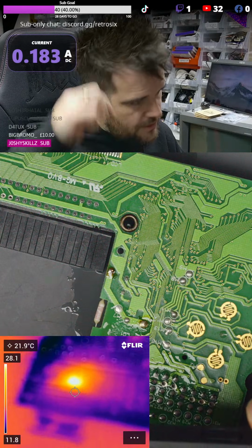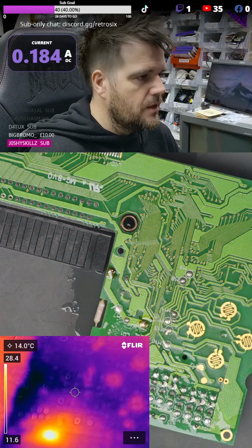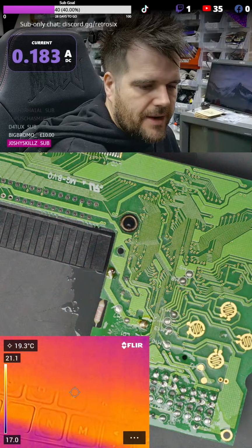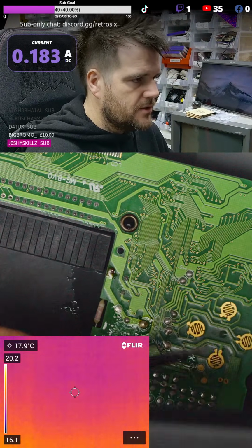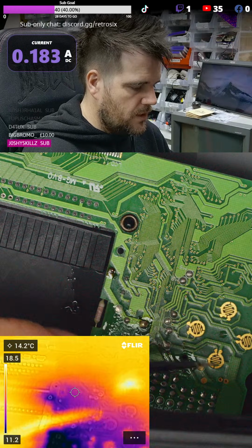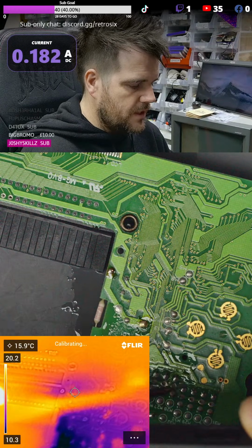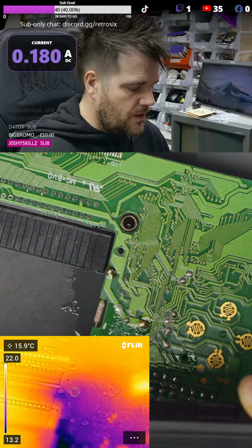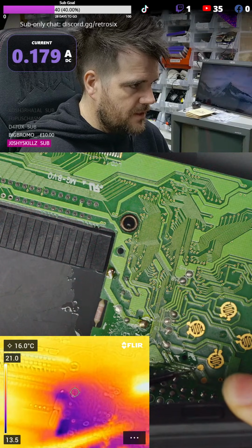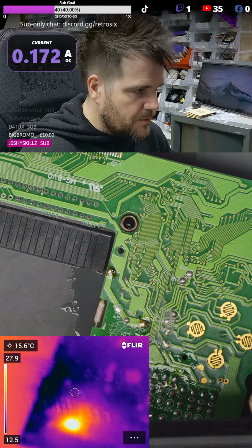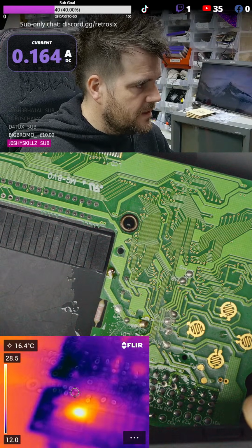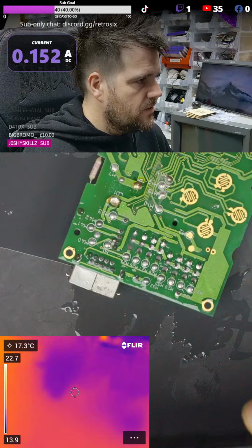What you'd now try to do is go, right, where's the short? And the best way I do is to get a pair of tweezers, soak them in IPA so that they appear cold on the thermal camera, or at least visible. So you can see on this, if I'm wafting the tweezers in front, you can just about see they're there. So you can see that tip. And then what I do is aim at the hotspot, move my tweezers in, and let's try and get this a bit more.